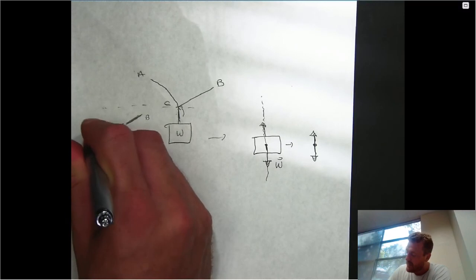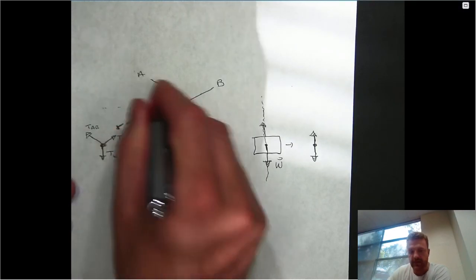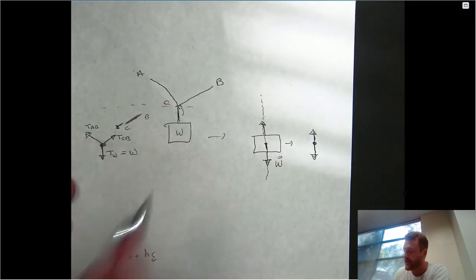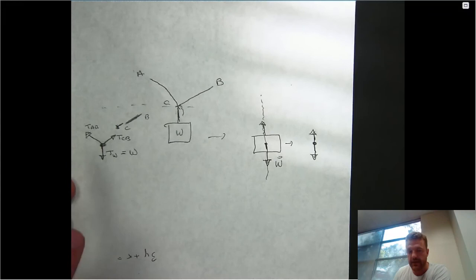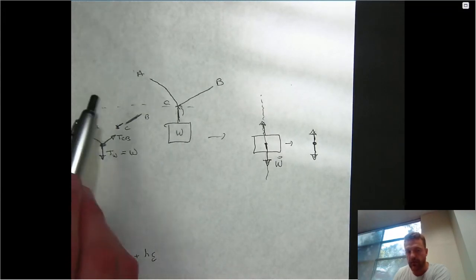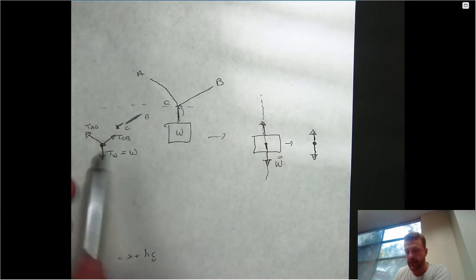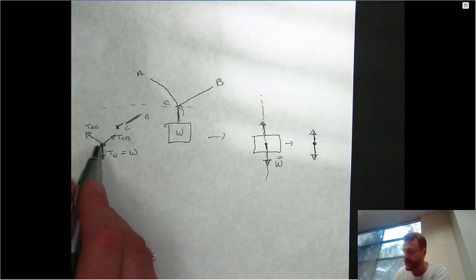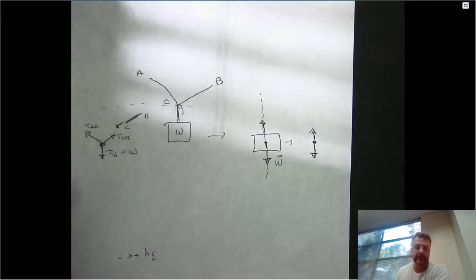I don't want to do the problem for you. From the geometry that you're given up here on the ceiling, you can actually determine the geometry of these two forces. However, the big picture of what's going on is that the tension in these two cables serves to counterbalance the weight. Both of them have a vertical component, which offsets the vertical component of the weight. Cable CB pulls to the right. That's counterbalanced by the tension in cable AB pulling to the left.